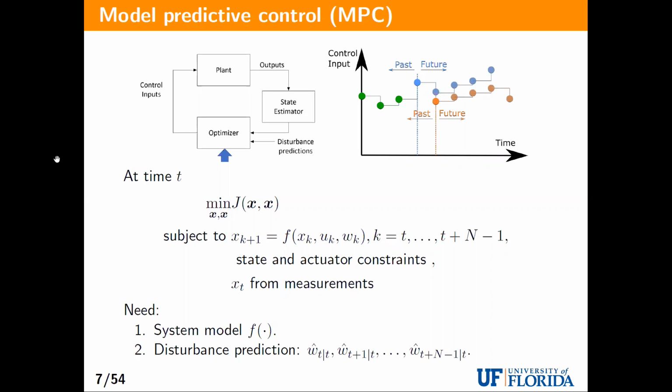So U is the control decision. That may involve airflow rates, fan speeds, chiller set points, etc. And the W is the disturbance, that's like outside air, outside ambient conditions, weather. So that will lead to some temperature and humidity in the building. And there is a relation between the two, which is this equation. So from the current time to some time in the future, you plan for it and solve this optimization problem. And whatever comes out of it, you get a plan that tells you the optimum thing to do from now till the next 24 hours is this.